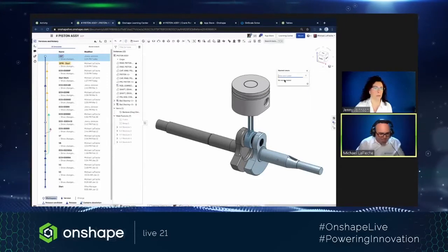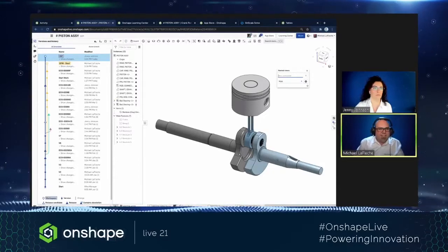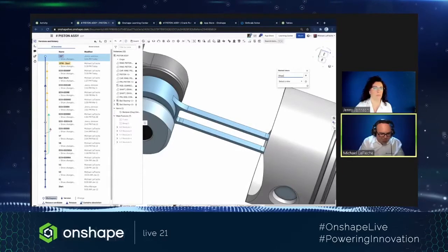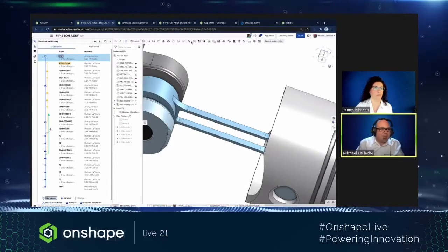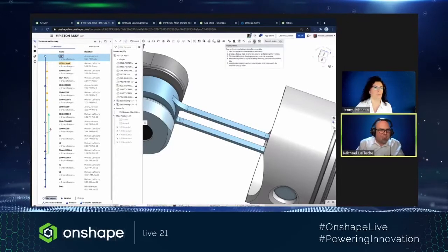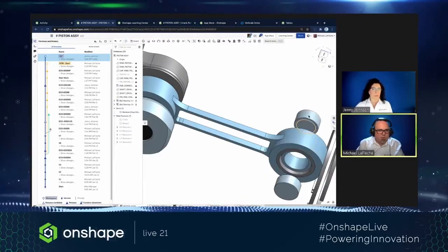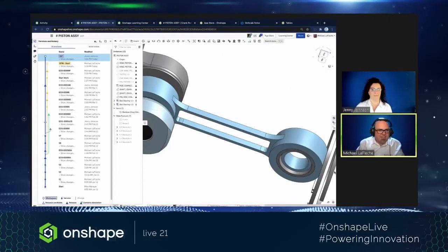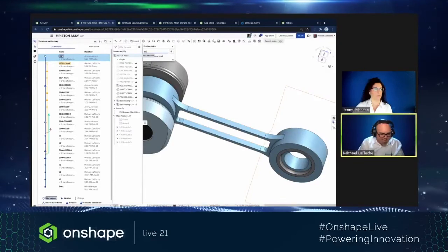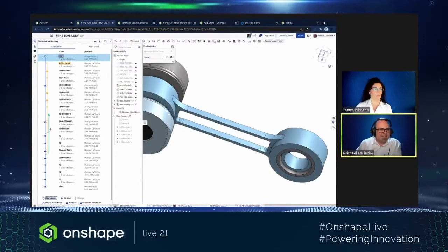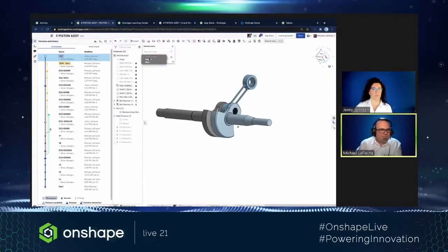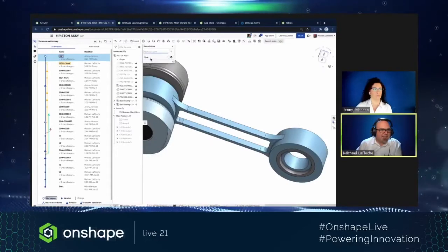So I have this named view. This is my main view, I'll call it, right? And then I'm going to zoom in over here, and this is going to be stage 1, I'll call it. You can couple these with named positions and view display states as well. So if I wanted to hide this, the letter Y button is your friend in this case, right? So I'm going to hide stuff over here, and I'll call this out as a display state, and we'll call that stage 1 as well, just so I have a nomenclature to go to. So now if I'm over here and I get back to my named views, when I'm here at stage 1, I can get back there, the main one.